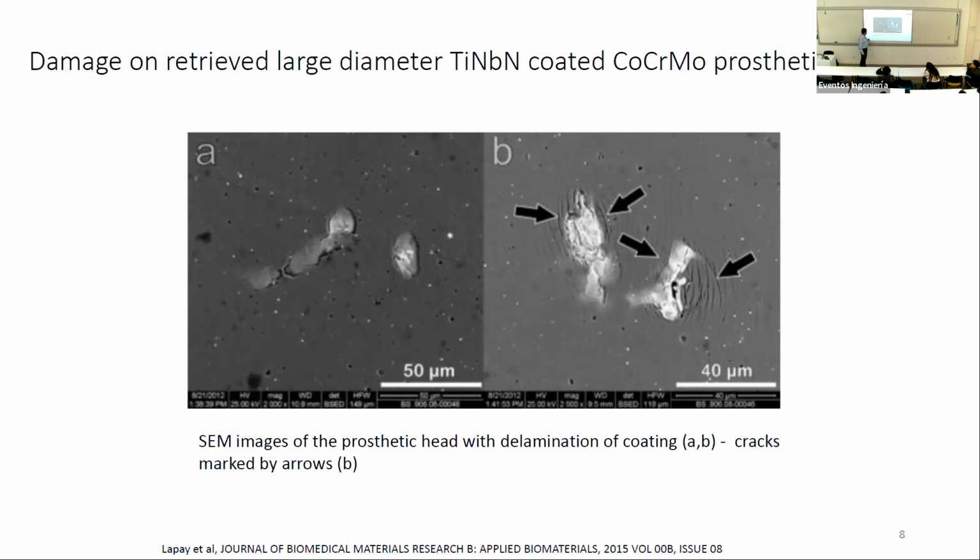And over here, in this case, we're seeing quite a lot of defects, pits inside the coating, and some blisters there, which probably have occurred because of corrosion underneath the coatings, and something which is kind of similar to the type 2 corrosion wear that we have seen before in this schematic.